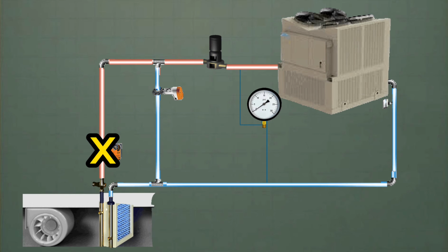So now I need to find the bypass valve because something's going on with it. There's an issue there. The bypass valve is not passing enough flow and the machine's tripping out. So I go and I find the bypass valve, and what I found was a little 3/4 inch Belimo valve that was bushed up to the 4-inch chill water line. So when I walked in there, the thing was just screaming, and we had no flow through the machine because the bypass valve was dramatically undersized for the system.